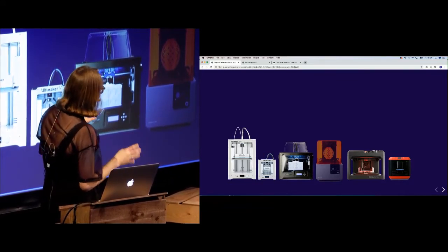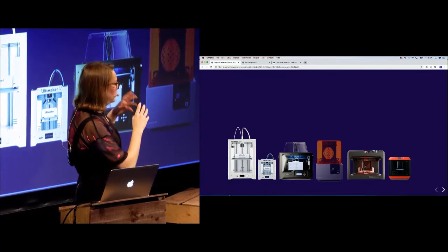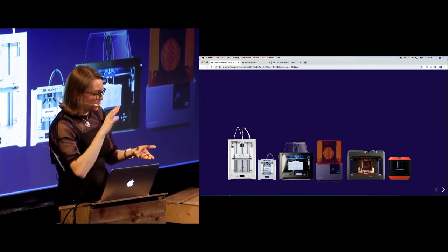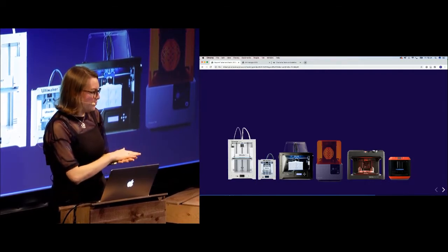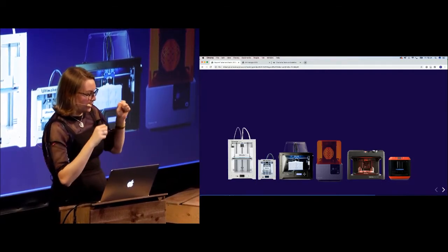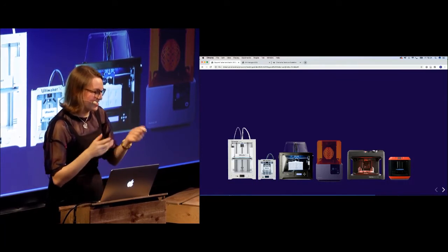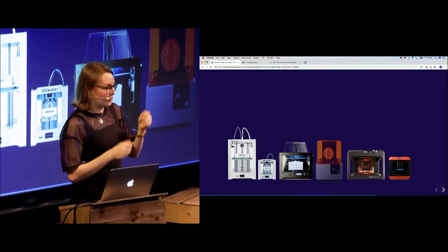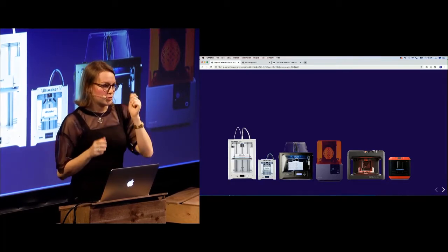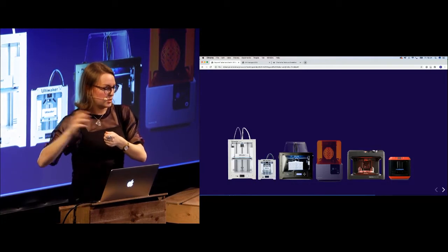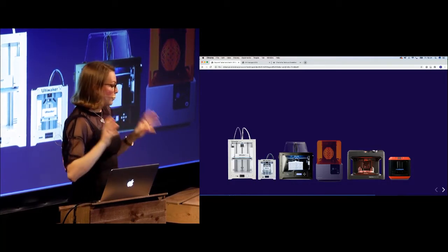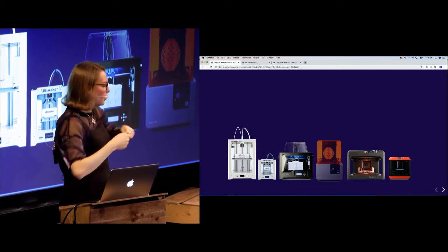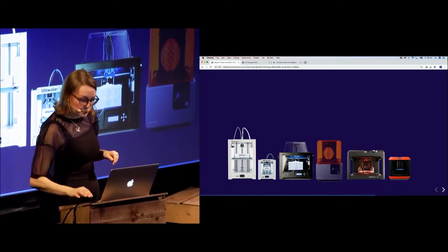And the way you would usually do that with a 3D printer is that you would 3D print the thing in plastic. You'd make a mold of that in rubber, and then you'd cut that out of the mold, and then you'd make a wax copy of the thing. Sorry, this is getting quite complicated. I'll explain that process more later. But you make a wax copy of the thing that you originally had in plastic, and you'd use that with this traditional casting process to make it into metal. But I can't do that with my things because they're so delicate and windy. You wouldn't be able to cut them out of the mold. So this wasn't really an option for me.